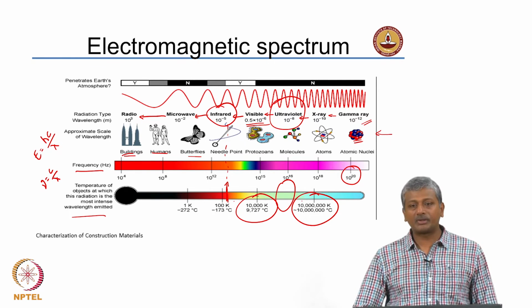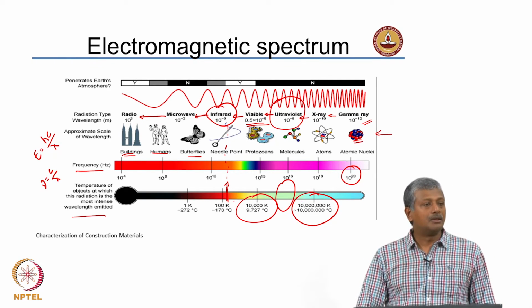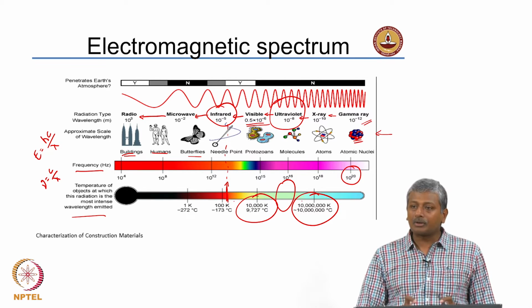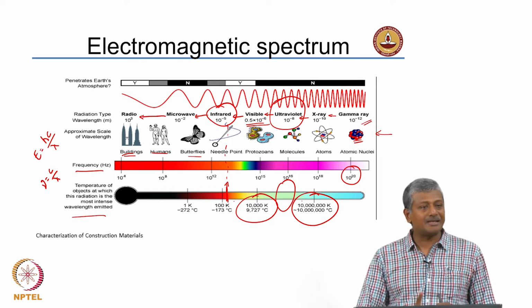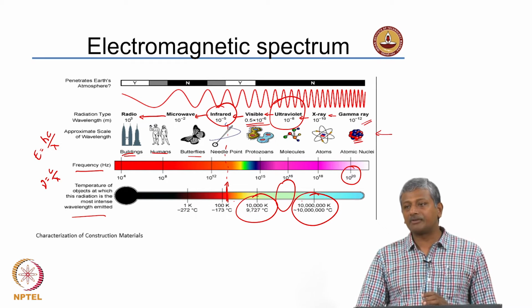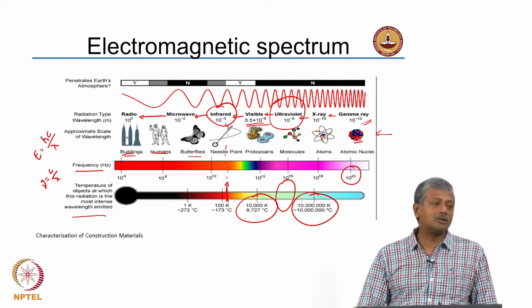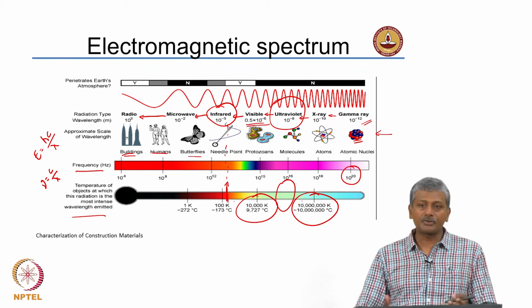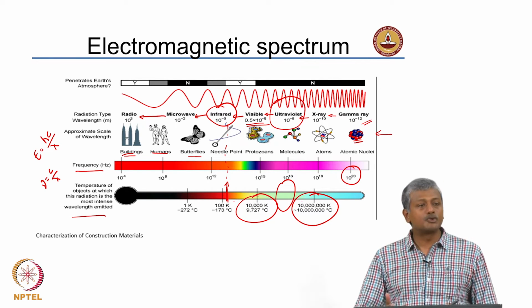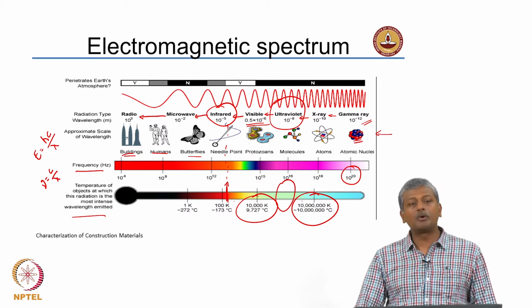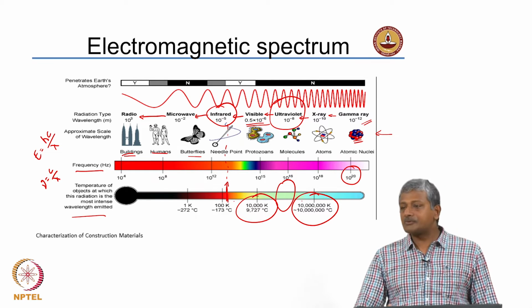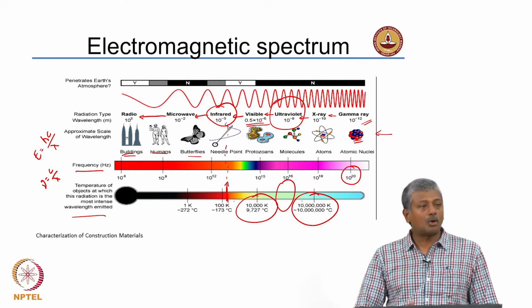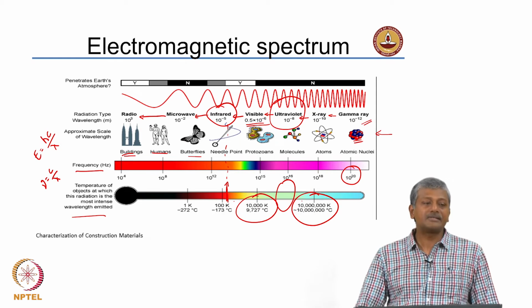We try to ensure that we have a very high density material in the lining or in the shell of your nuclear reactor, so that all these rays are absorbed significantly and do not get transmitted out of the reactor. So, typical materials used for shielding, if you talk about metallic materials, it is usually lead. Lead is a very high density, right, but lead is very expensive. So, one alternative that people have is high density concrete.